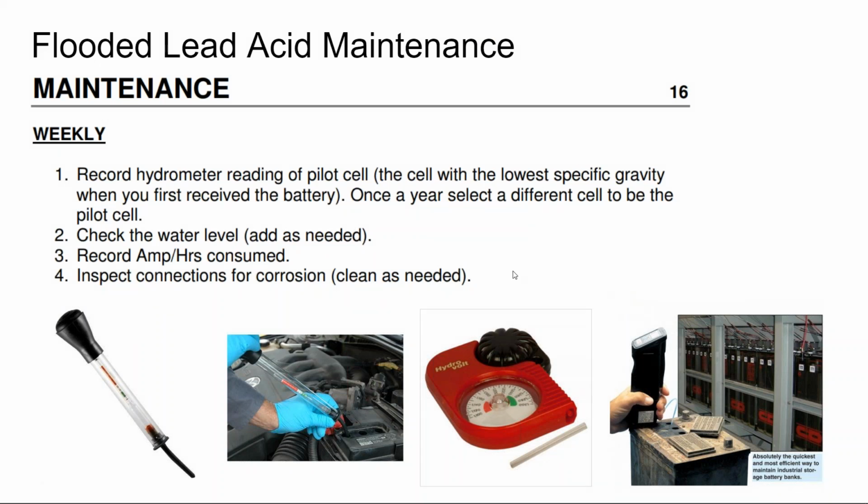I talked with my battery manufacturer. I said, look, they don't have to do this on lithium-ion batteries, which are sealed, so you wouldn't be able to do it anyway. Well, if I put current transducers on my battery and I'm building a dust-free, temperature-regulated battery box, do I have to read the specific gravity of the cells, which the warranty says is an every 2-week task?